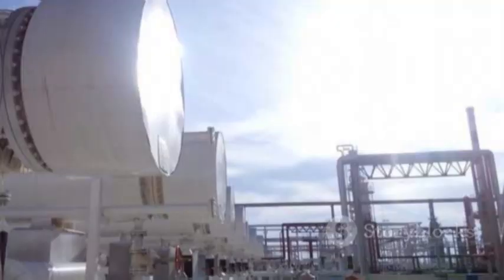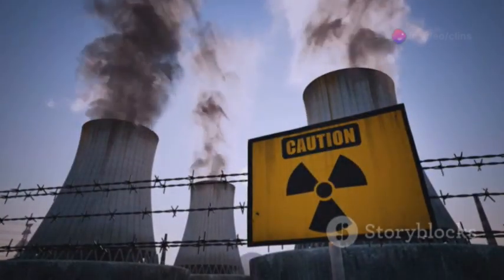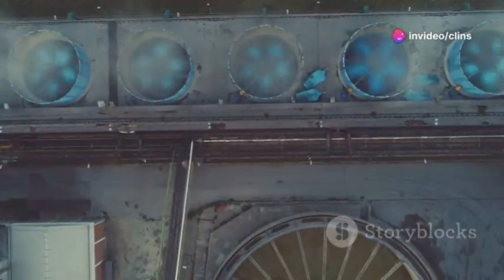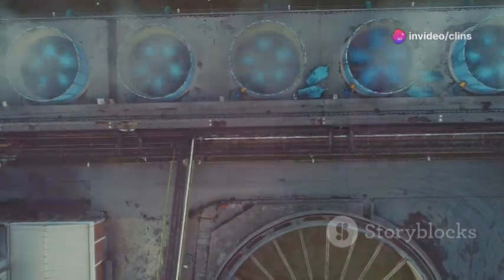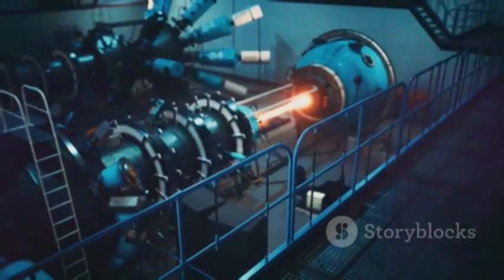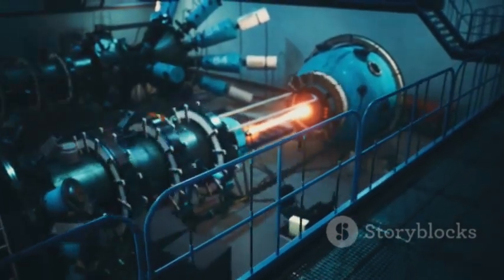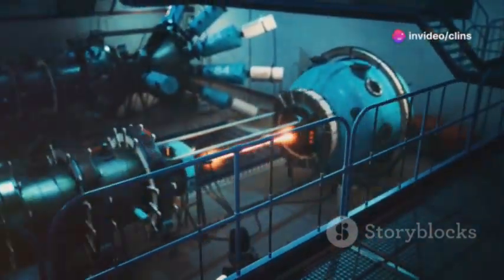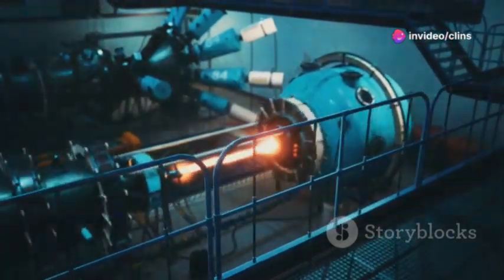Next, we have heat exchange. The heated coolant transfers its thermal energy to a secondary system to produce steam. This steam then drives turbines connected to generators producing electricity. And lastly, control mechanisms are crucial. Control rods made of materials like boron or cadmium are inserted or withdrawn from the reactor core to control the rate of the fission reaction.